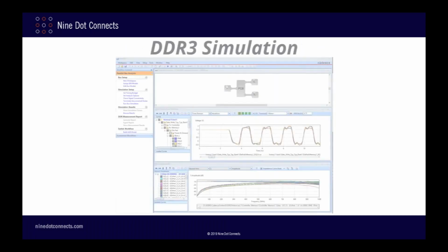Okay, now that we have a full design, let's look into what it takes to actually do the simulation. As I mentioned earlier, we're now wanting to look at the higher level signal timings and interactions, and will therefore now use the Cadence System SI program. System SI, as the name suggests, is designed to perform the system level timing analysis we need in order to verify the operation of our design.